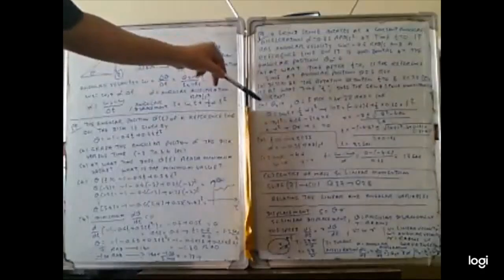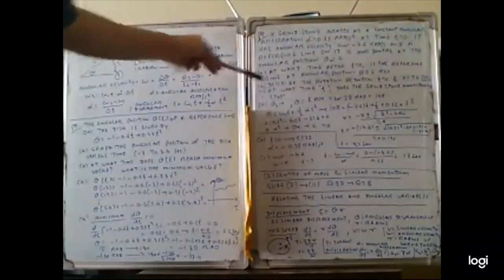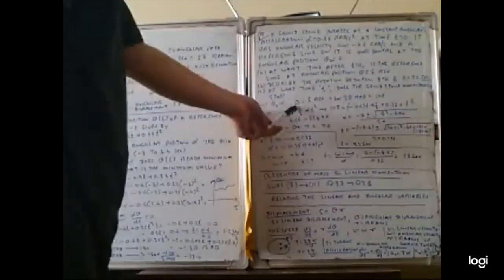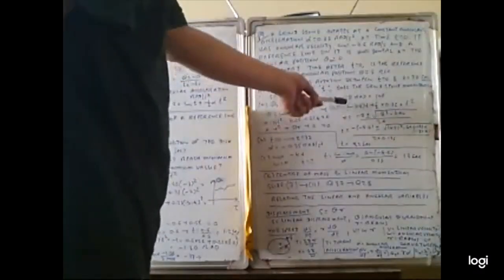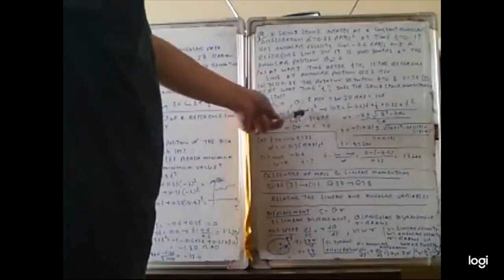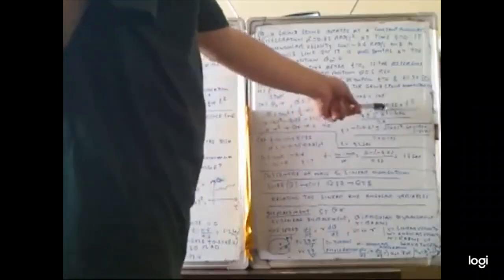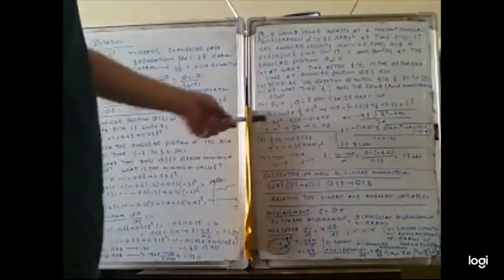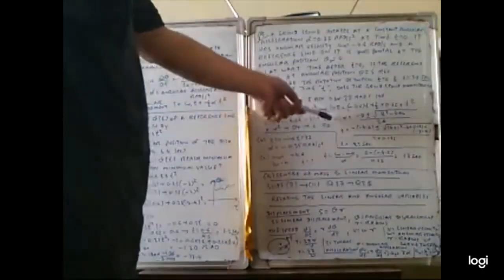So we have to calculate: the initial angular displacement theta 0 is 0, and the motion goes through 5 revolutions. So theta is equal to 5 revolutions, which can be calculated as 5 multiplied by 2 pi radian, so we get 10 pi. So we can calculate theta here. Theta is omega 0 T plus half into alpha T squared. So 10 pi is minus 4.6 T plus half into 0.35 T squared. Then we get 0.175 T squared minus 4.6 T minus 31.4 equal to 0.